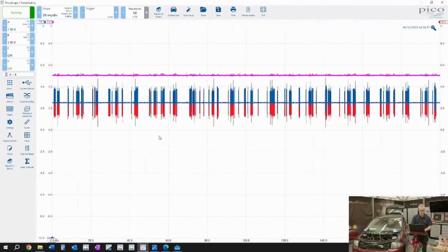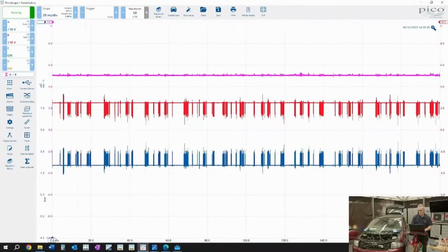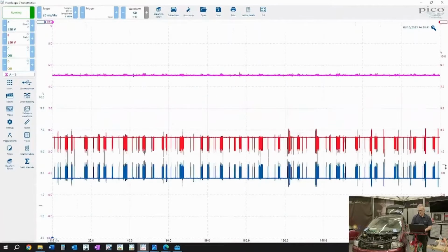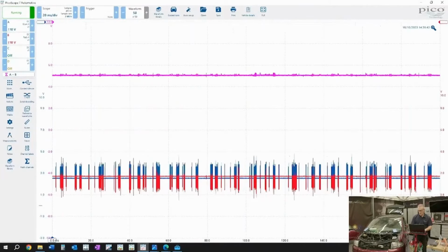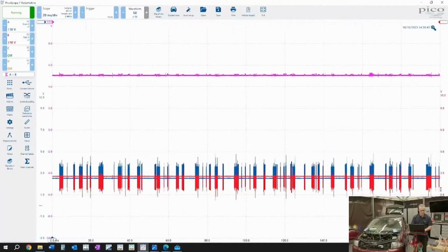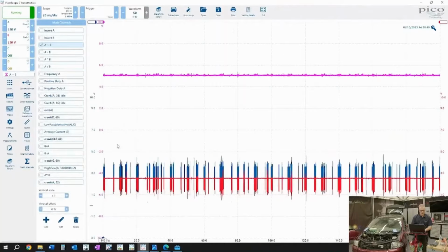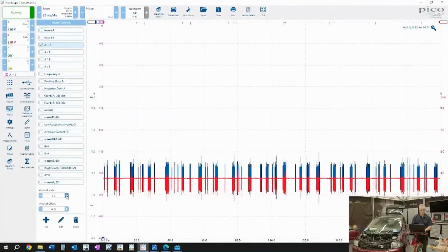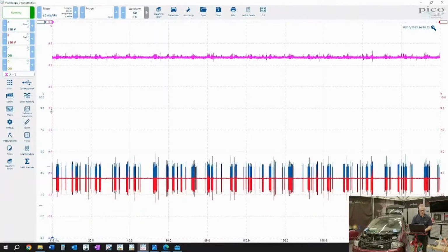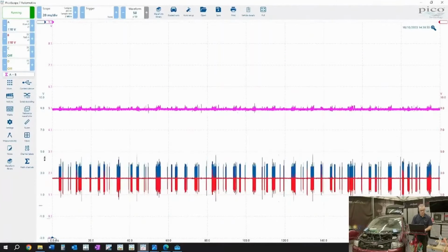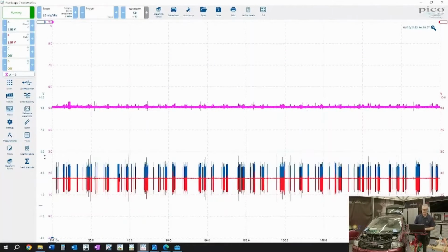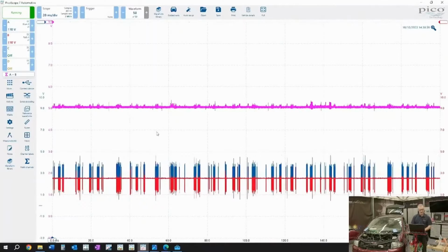What I'll do, I'll just click on our software. We can drag these waveforms out of view, and I will then change the scaling for the math channel. So we'll put the math channel at something ×2, and the reason being I can bring that down to around 5 volts in the scope view.